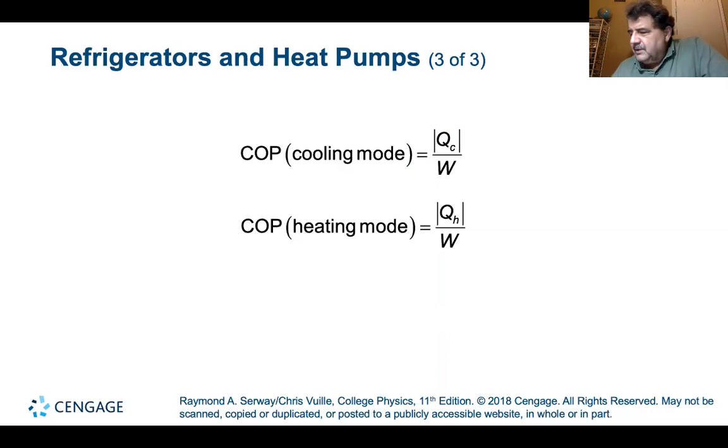The coefficient of performance, the COP, in the cooling mode is Q cold divided by the work. Yes, that is the energy from the cold reservoir divided by the work performed. The coefficient of performance for heating mode is Q hot divided by the work.